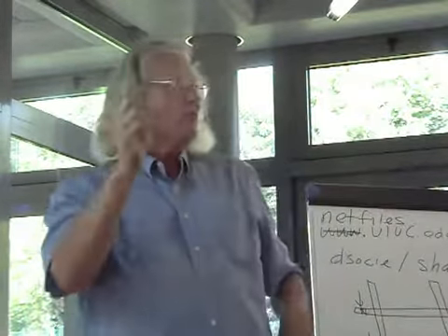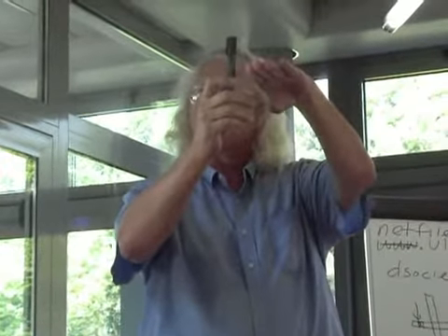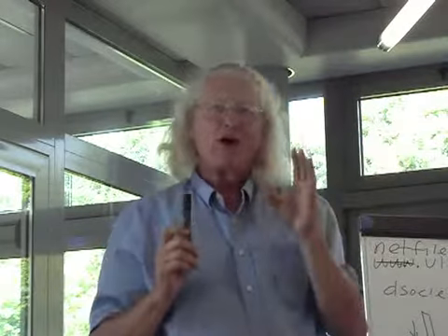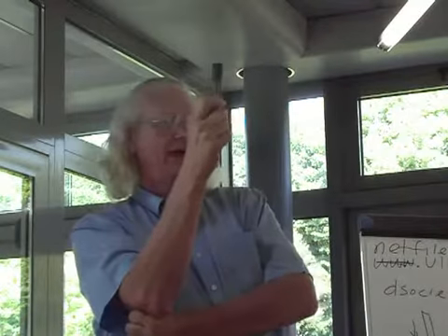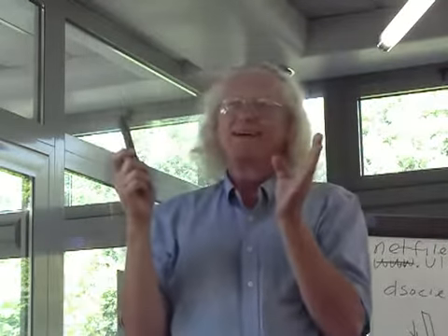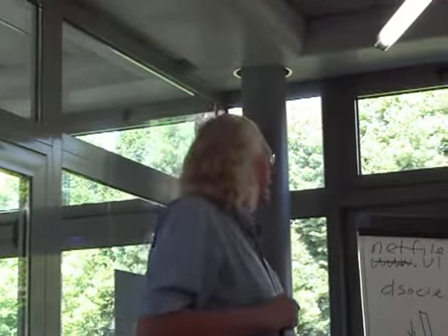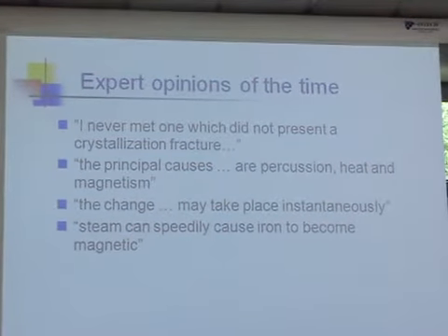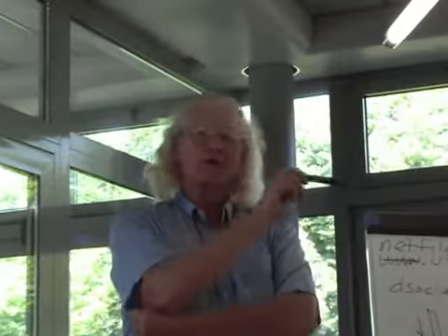And then you look at a fatigue fracture of the same material, and of course a fatigue fracture is very flat across, very much like the fracture of a rock. And so they thought that somehow all of the materials mysteriously crystallized, and after they crystallized, then they broke. That there was some material transformation. We know, of course, that's wrong. But it doesn't stop people. If it happens, you need a reason for it happening. Now, it's not a surprise that almost all the failures happened in the locomotive part.